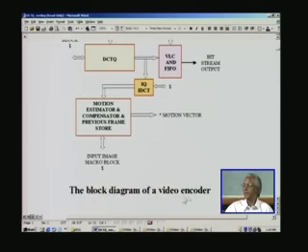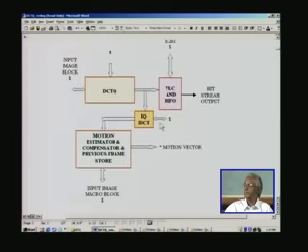So this block diagram of a video encoder is shown here, and as explained before, we first take one block of image and then apply DCTQ. Out come the corresponding 64 coefficients here, and if you do the inverse operation you can recreate the very same image that you have put in here, and that is what is called the reconstructed image, that can be stored in RAM here, and that is what is designated as the previous frame store here. You need this because in order to perform motion estimation we need the previous frame, otherwise we cannot see how to process the motion actually.